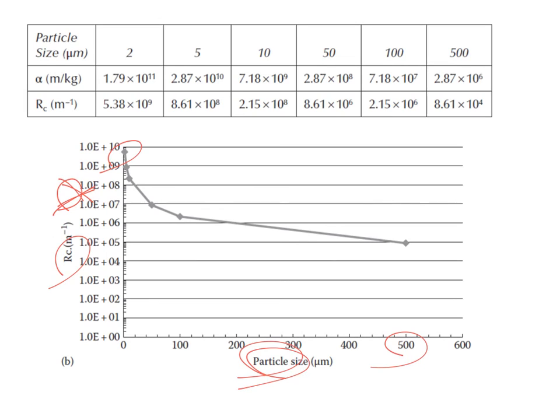or the plugs with a size of 2 micrometer, with a size of 500 micrometers, this is a huge difference. So again, we have to maintain this microbial plug as large as possible, and we have to prevent the production of submicron particles or the small particles, because they will actually increase the cake resistance, leading to a significant reduction in membrane permeability.